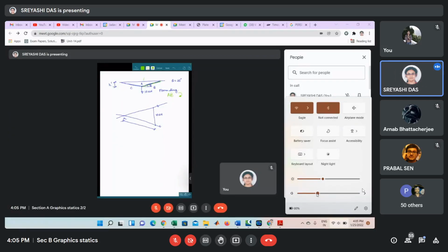So AB means the member force. If we take this joint from where this 10 kilonewton force is acting, then if we say AB, that will give us the direction of force according to this joint. Here AB means this direction, A to B. So here also the same direction will come, thinking about this joint.